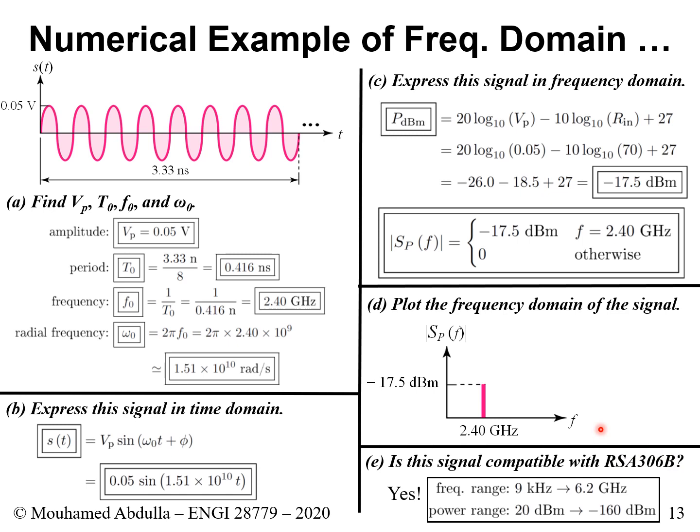Now this is an example that I gave you, and in reality this example resembles a good signal for Wi-Fi. 2.4 gigahertz is what you would essentially see with Wi-Fi. We said Wi-Fi has two possibilities, 2.4 and 5 gigahertz, and having a power of minus 17.5 dBm is not bad. It's actually a relatively okay signal quality for Wi-Fi.